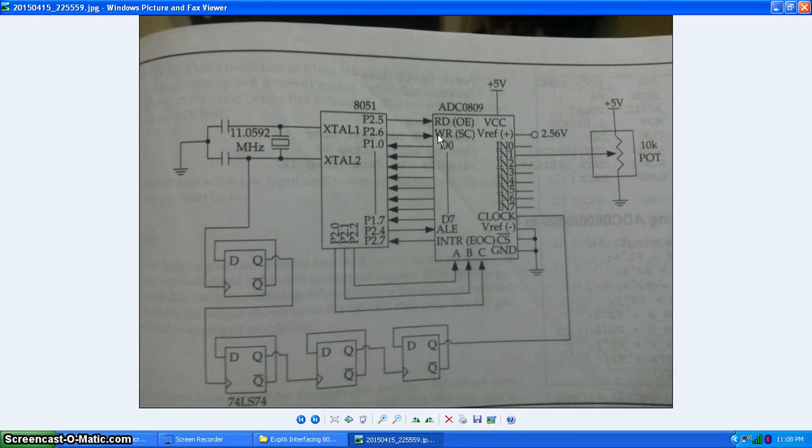These things will be clear with the help of the waveforms. Next we are going to view those waveforms. Then output enable, again a signal from the microcontroller. The only signal going from the ADC to the microcontroller is INTR, which is also called end of conversion.